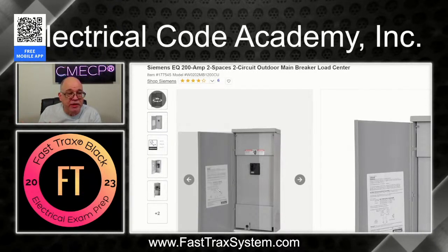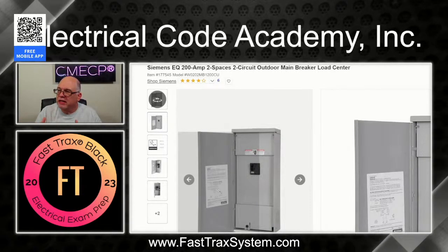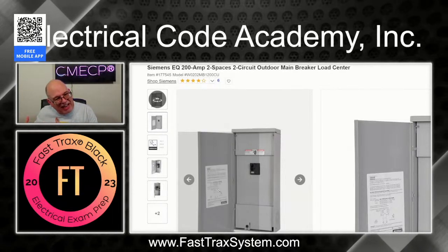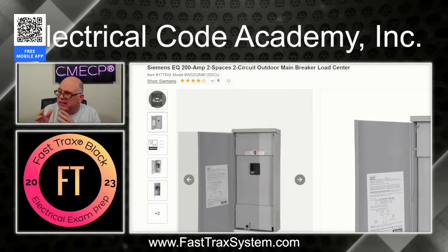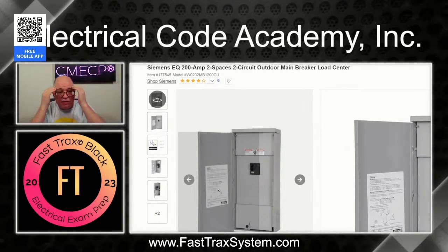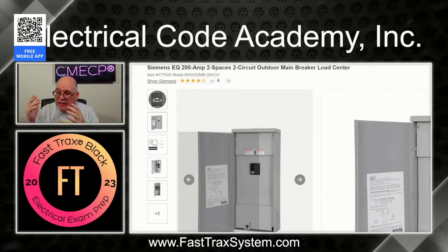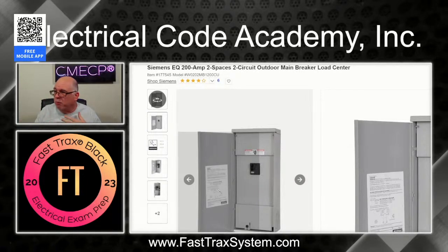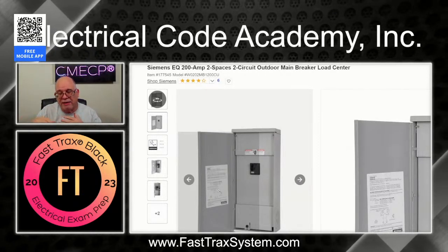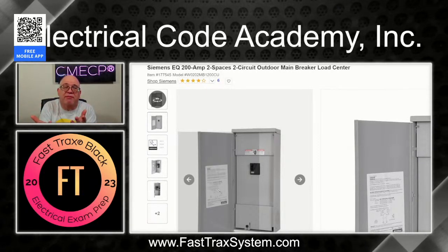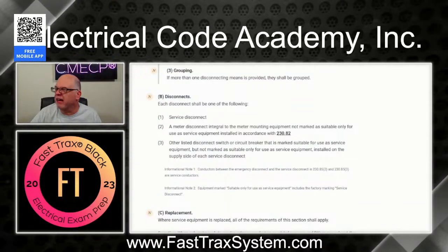Now, again, you could put a NEMA 3R panel with a main breaker and breakers in it. That's your option. It's just more difficult to figure out how I'm going to get my cables into it, right, than something like this. So an additional $174, I don't have to worry about it. I just take some SER on the load side of this thing in and hit a panel, and then I don't have any problems, okay? I'm willing to pay $174 to not worry about the headache. And I want the panel where I want it. For me, I just don't like it outside. You may love it outside. That's just not me. That's the beautiful thing about it, right? To each his own.